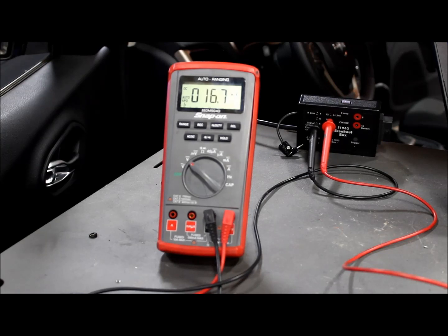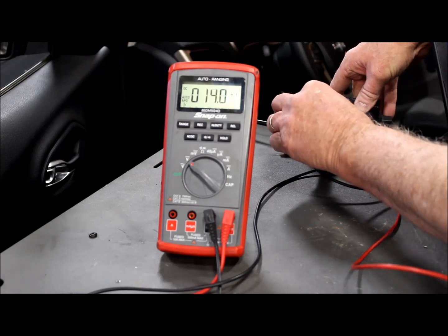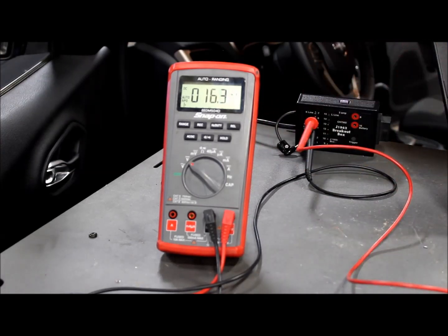So when I turn the key on, the bus should go active, and we should see on the high somewhere between 2.6 to 3.5. So I'm going to go back into my CAN-C high or plus and go turn the key on.